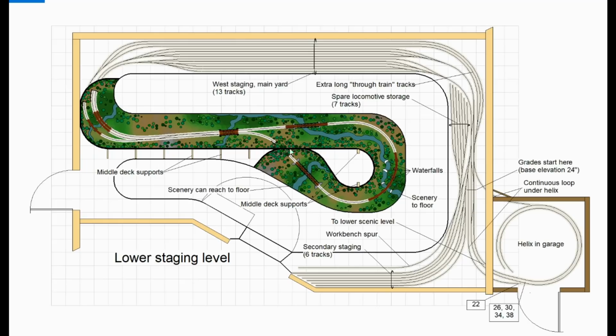And then the straight part of the central backdrop will also need to be structural. So I would recommend, instead of just a piece of masonite, start off with a sheet of 1/2 inch plywood to anchor all the C pieces together, and then laminate the masonite on top of it. And then at the end of the peninsula there is room behind the backdrop for a couple of 2x4 legs that go all the way from the floor to the second level, thus solving the potential structural problems on the most critical point.